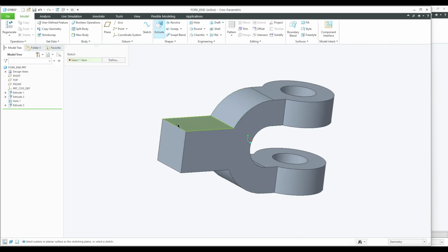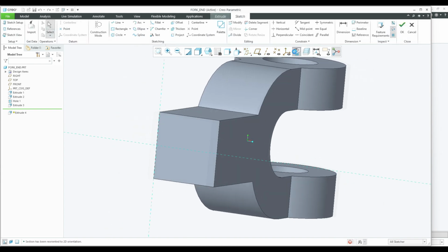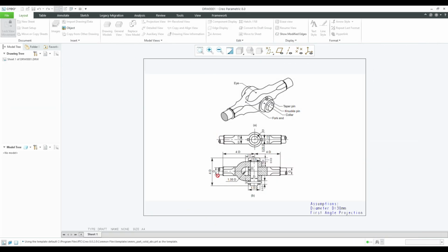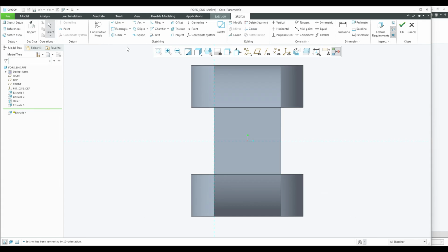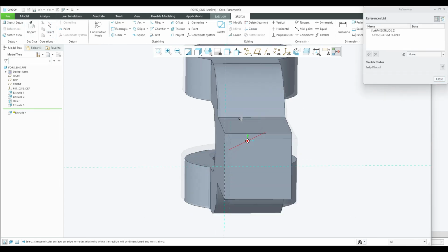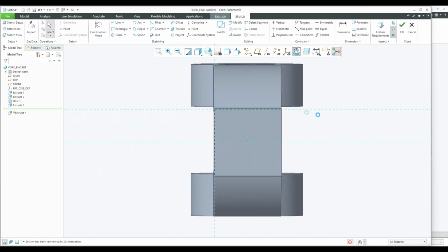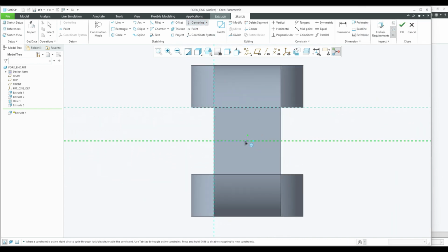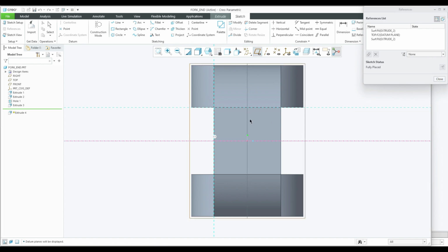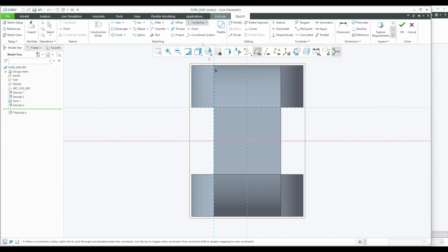Next we are going to create a shaft at this end, which is actually equal to the diameter value of d. We can see here it is a circular shaft. So I'm going to take a reference from this point to this point. Make it a sketch 2 view. I'm selecting this horizontal axis, and I'm going to select a vertical axis. Instead of that, I can select this plane as a reference, so that I don't have extra dimensional constraints here.